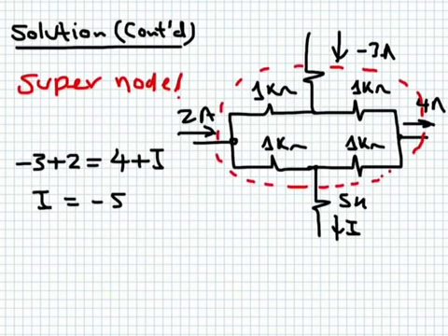The easier way is to take back KCL to its origin. KCL is simply saying build any closed circle and the sum of all currents entering that circle is equal to 0. So what I'm going to be doing, I'm going to build a circle that encloses my circuit, and then I say the sum of all currents entering this node is 0. This is the origin of KCL. We call this a super node. Why is it a super node? Because you can have many components inside it.